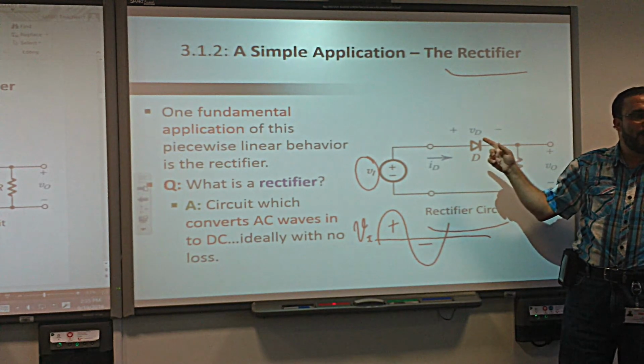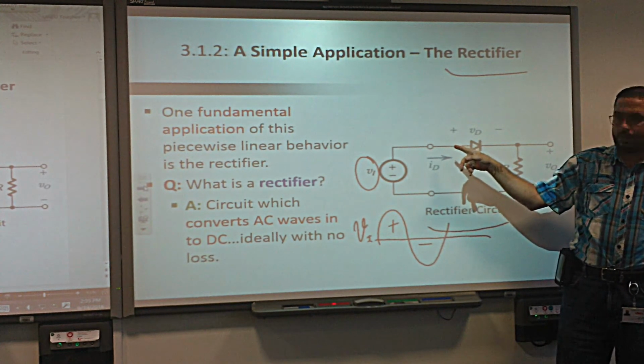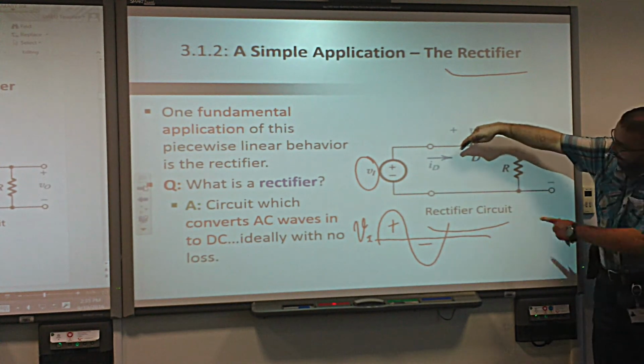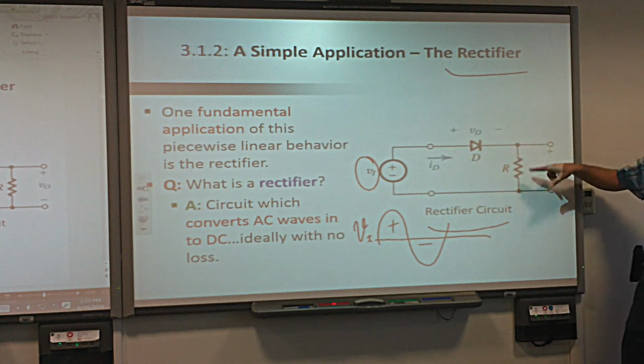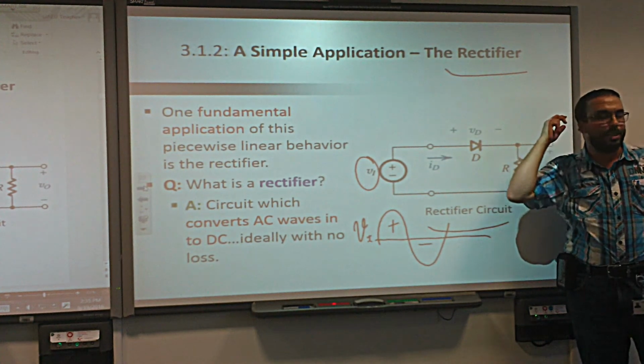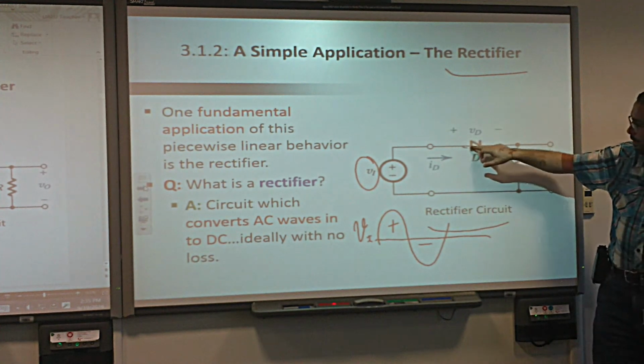Forward. Why? From positive to negative. Because this voltage is bigger than this, yes or no? Yes. Because we are applying here positive voltage across the resistor and the diode, like the same example we had just now. In this case, we replace the diode with what? Short circuit. Very good.